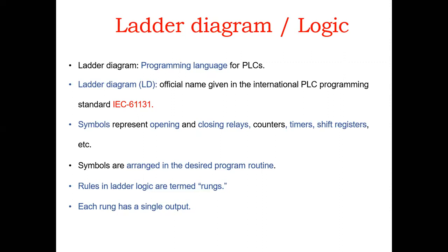If you want to program a PLC, we need a programming module. Here they are using the programming language of PLC. In a microprocessor they are using mnemonics, like that in PLCs they are using an instruction set. Here they are using ladder logic for processing the input and output. That is ladder programming. So ladder diagram is a programming language of PLC.